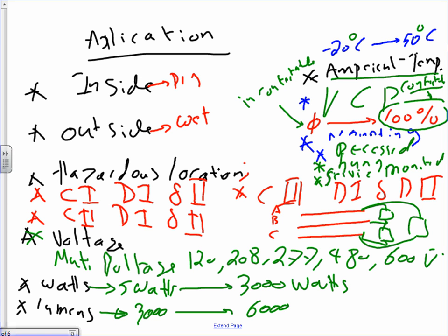Explosion proof fixture. So you have to ask yourself, is it Class 1, Div 1 and 2? Is it Class 2, Div 1 and 2? Or is it Class 3, Div 1 and 2? Class 1, guys, is flammable gases. Class 2 is combustible dust. Class 3 is ignitable fibers. Obviously, the worst is Class 1, gas and fluid that can ignite, gasoline and all this good stuff. So these are the 3 classified locations by the NEC code book you have to pay attention to when you put your fixture. Can I have thumbs up, Chad?